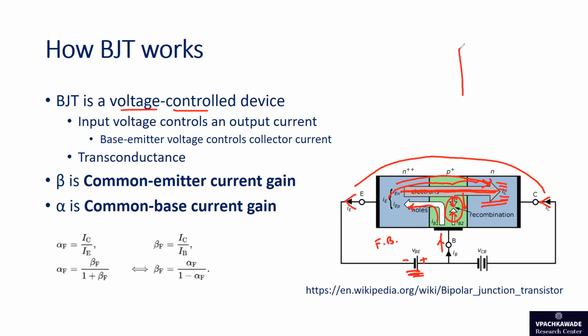So in terms of a graph, you can show it like this. You have VBE, that is the forward biasing, and you have the collector current IC. When you start from 0 volts and go up to 0.6 volts, junction J1 gets forward biased. It is simply a PN junction, so up to 0.7 there is a very low current, and after that you have a large current. That is your collector current, the output current due to the applied input voltage.